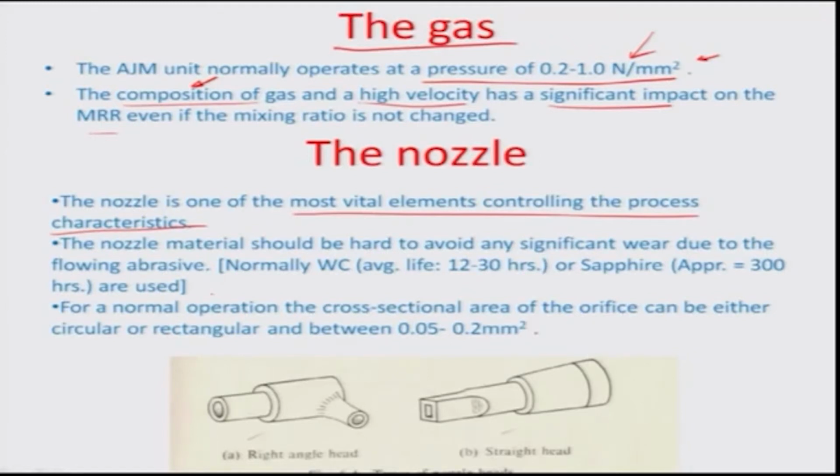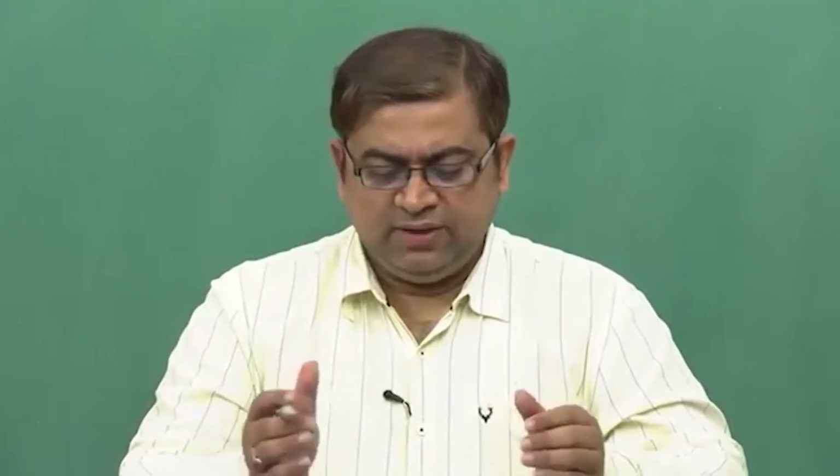If it gets deteriorated, then the distribution of impact, which would otherwise be a Gaussian on the workpiece surface, with the central particles being driven at the highest axial velocity and the particles emanating from the side of the nozzle having lower velocity, changes completely because of the deformation in the total cross sectional area of the nozzle.